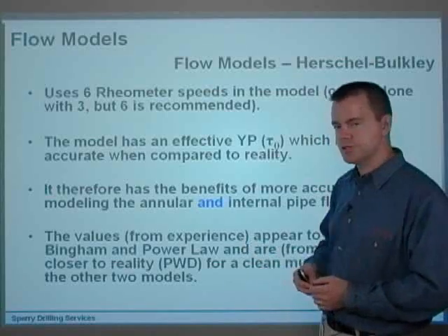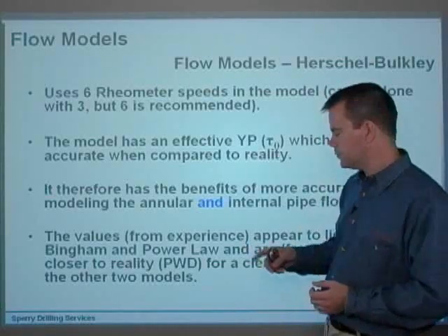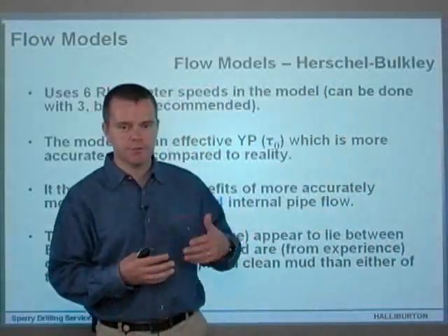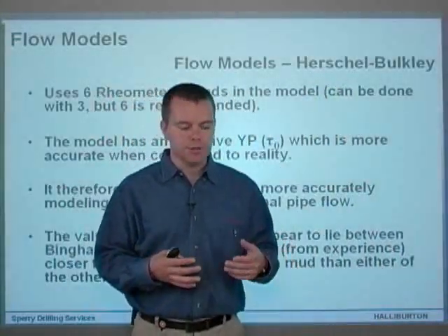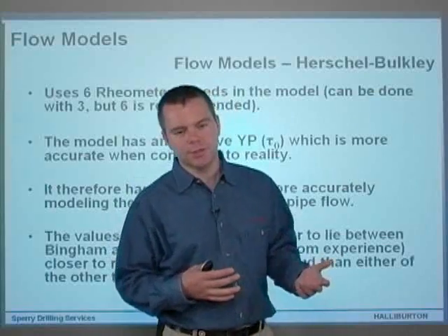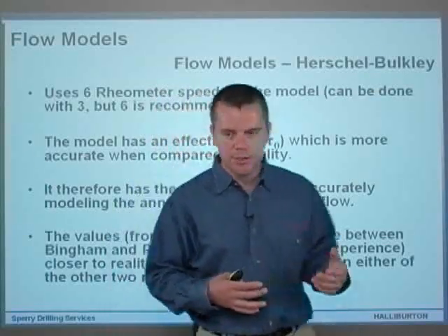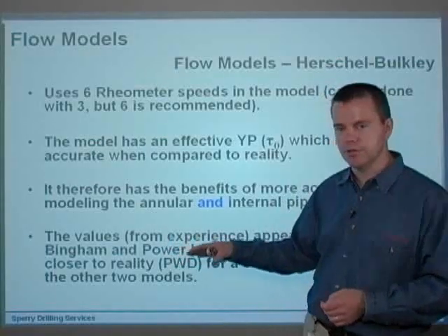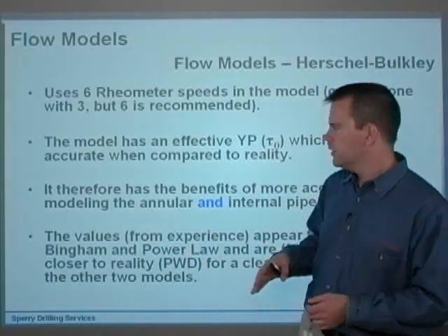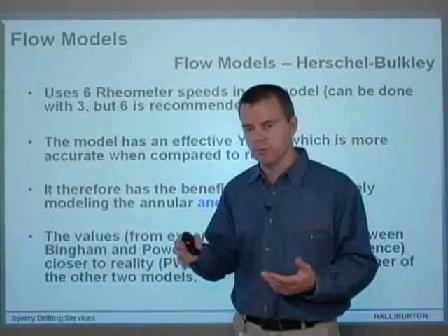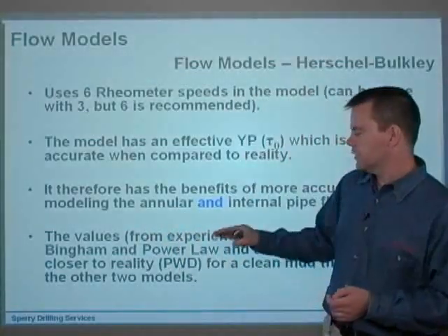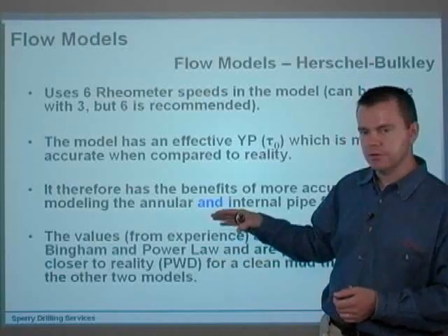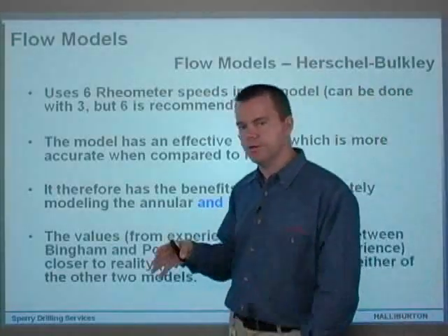And from my experience as well, looking at actual PWD data, when you've got a very clean mud, before you actually start drilling, before there's any cuttings in that mud, if you've got a clean mud and you start pumping it, then Herschel-Bulkley will actually be very, very close to reality, very close to that PWD reading for a clean mud. And the other two models won't. Basically, when I say PWD reading, your annular pressure reading, Herschel-Bulkley does model the annulus very, very well.